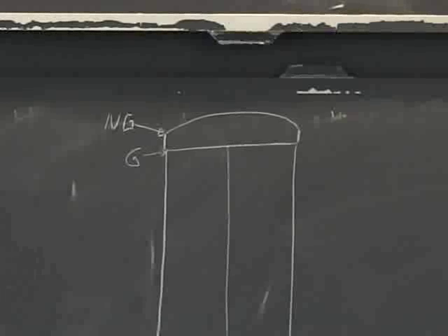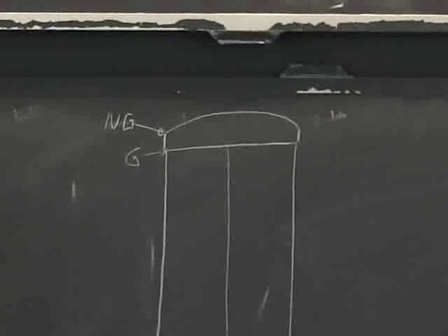Depending on the environment, you may be at risk for stress cracking as well. And stress cracking of welds is a problem because you have all these residual stresses. So if you take a plain piece of a stainless steel, for example, 316 stainless steel, and you put it in an environment that could generate stress cracking, it may do fine because it doesn't have high residual stresses.